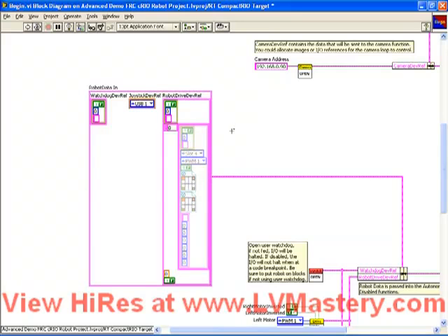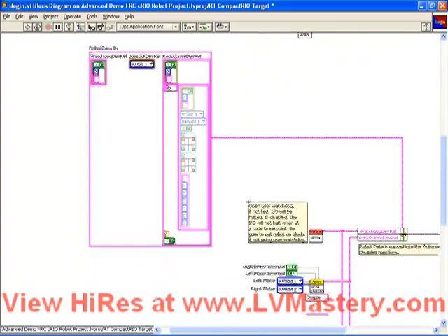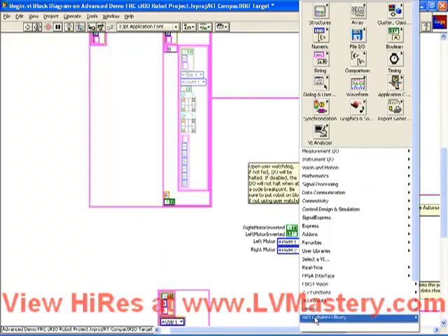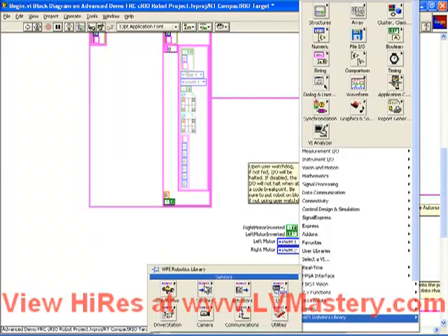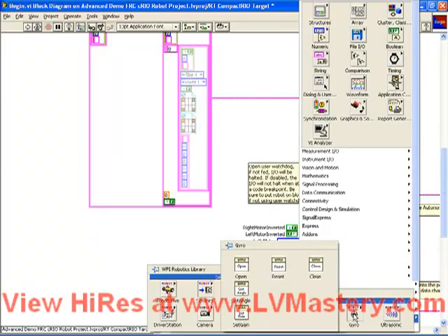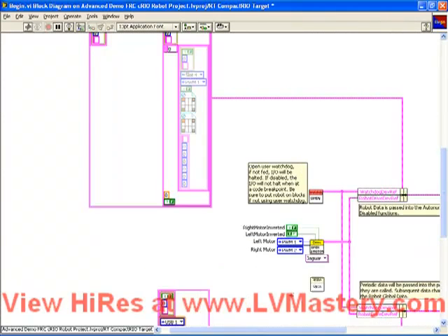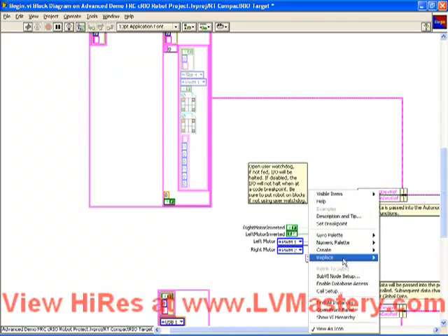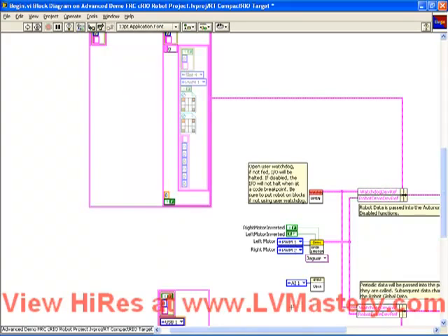Well, what we want to do now is to add a servo and a gyro. So we know that we're going to have to add WPI library functions to open both of those objects. So let's do that right now. We'll go to the gyro sensor open, put that down. We'll wire up its analog channel by creating a constant on the analog input of AI1.